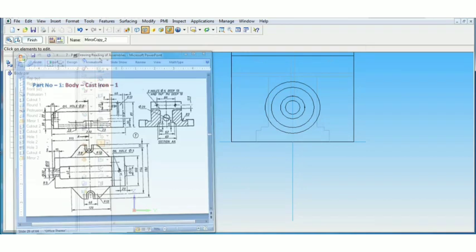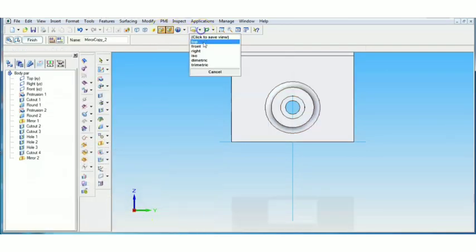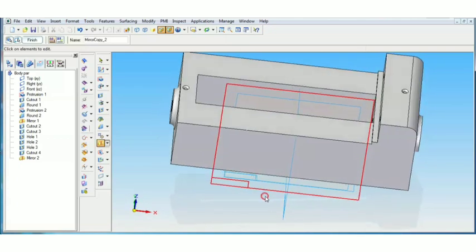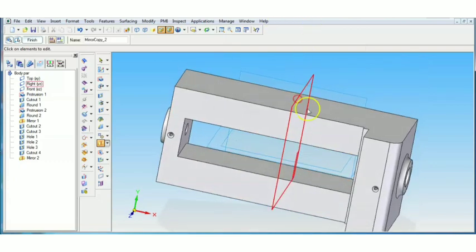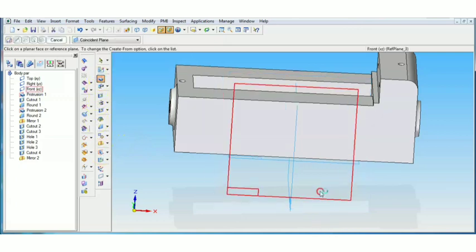So the part without wings is ready now. Now we just have to add the wings. Half of the wing will be drawn, the remaining will be added by mirroring it, and the same will be mirrored on the other side as well. To make that, we have to start with a protrusion.